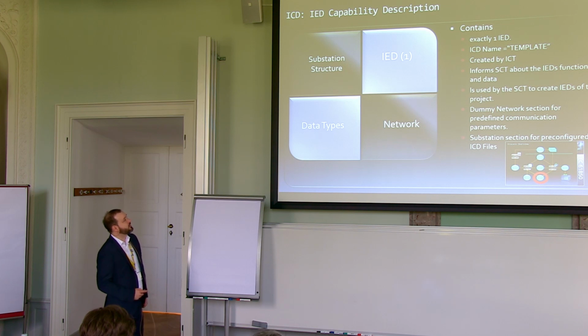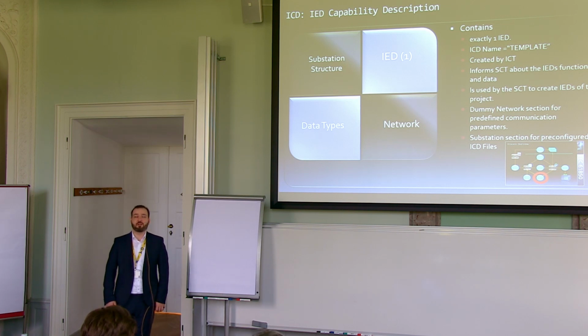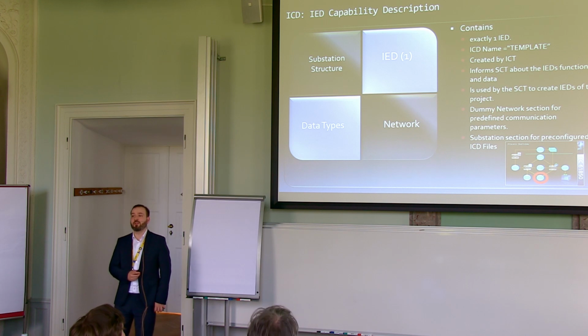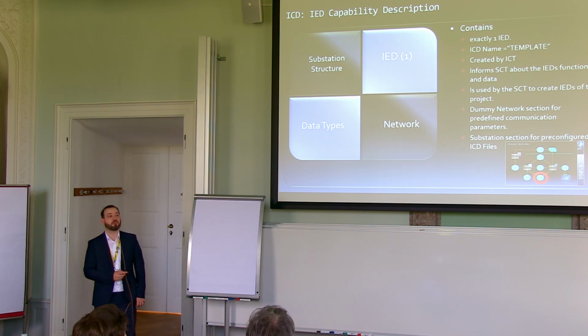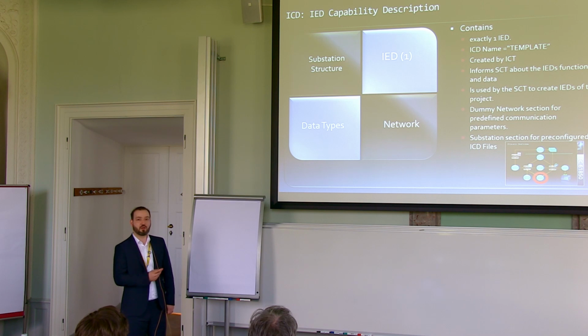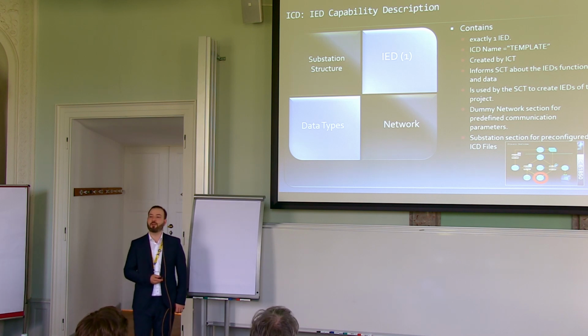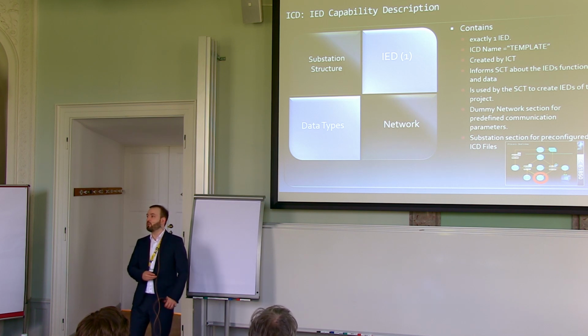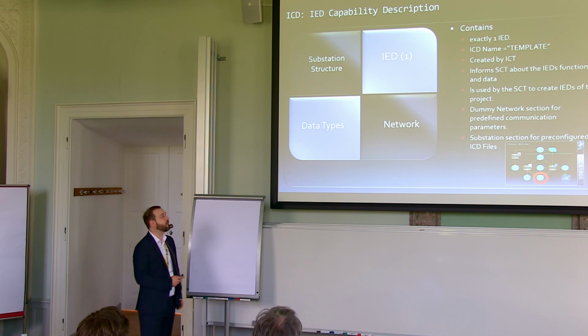You probably all worked with ICD files. They're very common in use, but just to summarize, these describe what the relay is capable of from a systems point of view. It doesn't mean that this is all the relay is capable of. You may have a very powerful device or a configurable device where only some of the functions are able to be used concurrently, and an ICD file then exposes one or the other function, or perhaps enforces some other restriction.